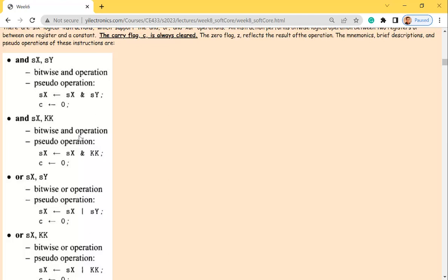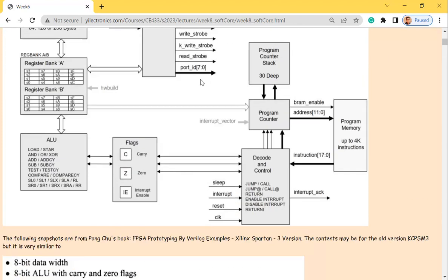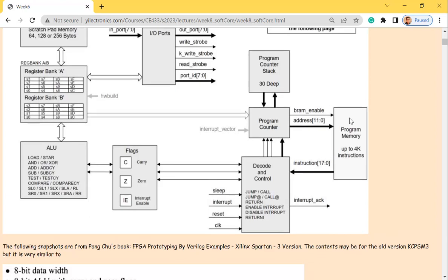So how to program it? Let's come back to this topic. Like I said, you have a program memory, but the Arduino has a bootloader. It will make the communication, bridging the computer and the program memory of the Arduino chip. It converts the code into something like machine code and puts it into the memory. Or the IDE compiles it, converts it into machine code, and sends it over.